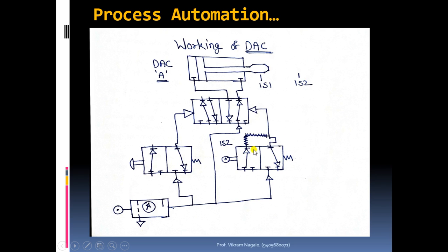And whenever this is getting pressed, as the air is coming at port 1, the input port of the valve, the block or the valve will slide inside the casing, and the air coming to port 1 will get passed to the output side, that is port 2, and that will get transferred to the right hand side of the valve.